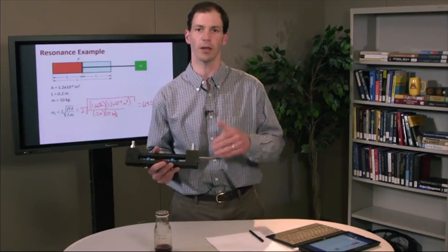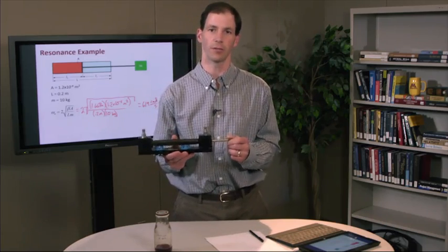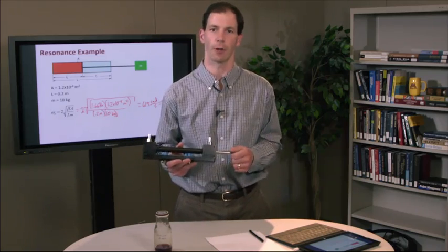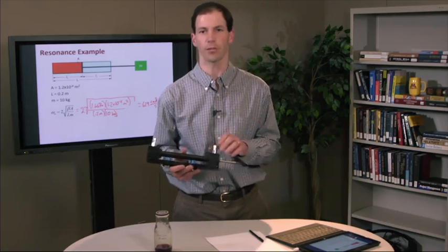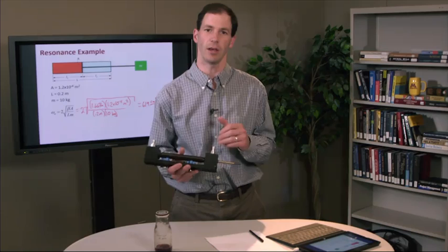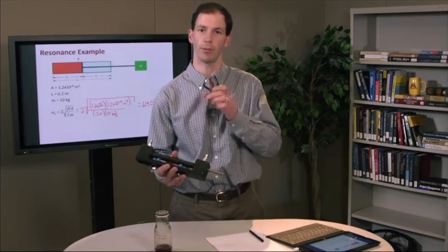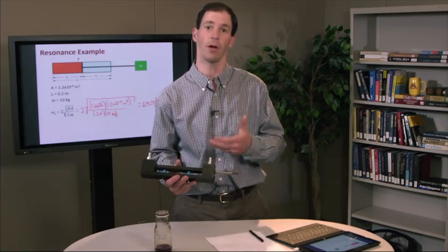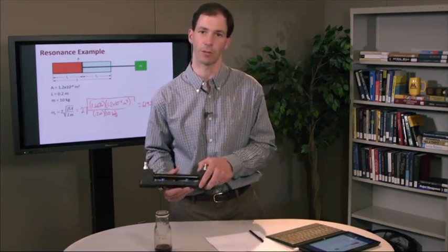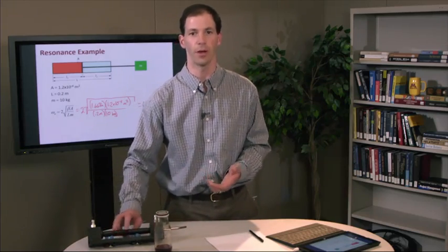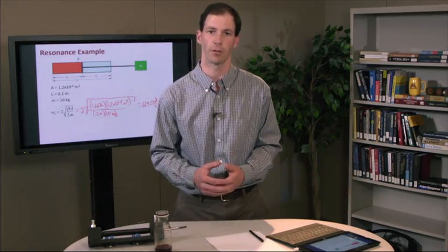So we are getting into the resonant frequency of some hydraulic systems, so we have to be careful how we're operating when we get to those regions, and there's some special things that we can do. One thing that I have neglected with this calculation is the additional hydraulic oil that would be between the valve and the cylinder itself. So there would be additional compressibility, which would further lower this natural frequency. So in some situations, a long, slender cylinder like this, we can have fairly low natural frequencies.